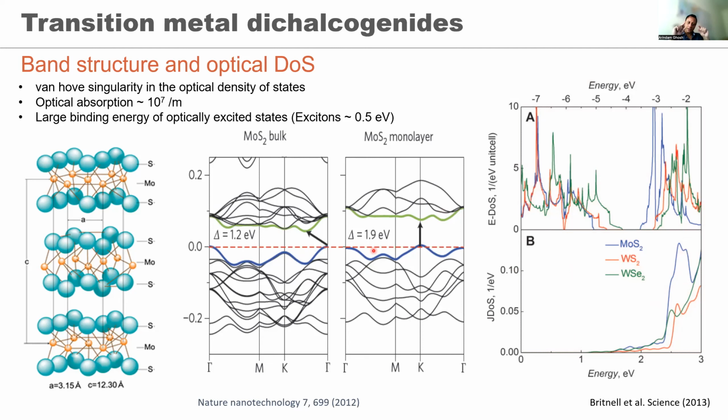And a single monolayer, a single molecular layer of molybdenum disulfide can absorb up to 5 to 6% of the optical radiation above the band gap of about 2.5 electron volt, which is unthinkable as far as silicon is concerned, because silicon, the similar kind of absorption requires much thicker silicon piece. So that's one of the key advantages of using transition metal dichalcogenides in any kind of optoelectronic design. And when you look at light matter interaction at the interface or with 2D, this is one of the key considerations that we have to keep in mind.